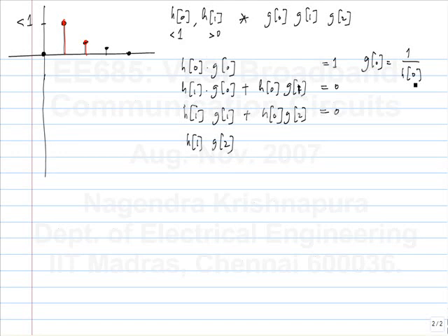Greater than 1. So that is one thing. Also, you need some kind of a gain in the equalizing filter because the cursor amplitude has been reduced. If it's followed by a decision block of the same sensitivity as before, let's say you have a transmitter and you have no channel or an ideal channel and you go to a slicer.